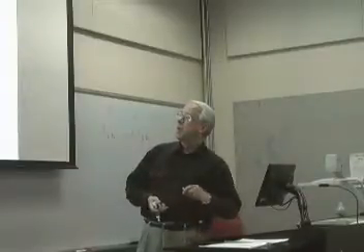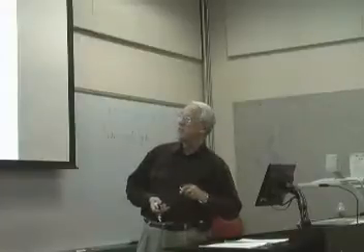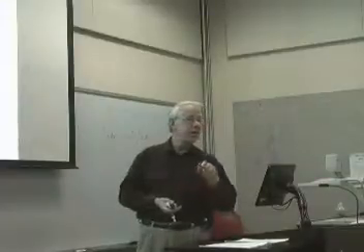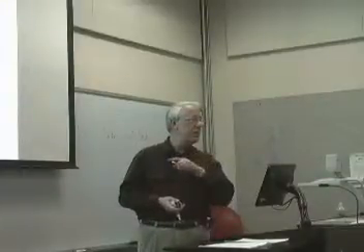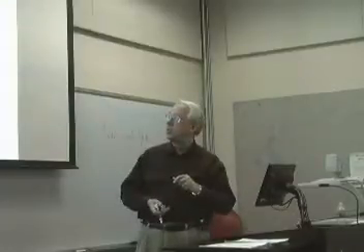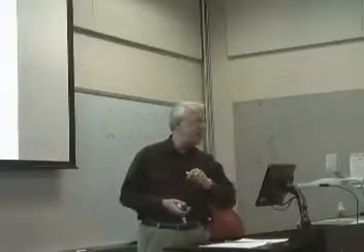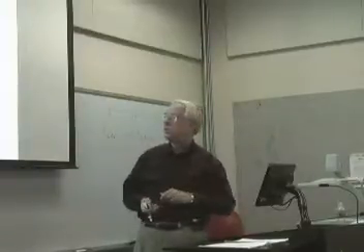This is what happens if you're going to add convection along a boundary. So the flux is just equal to that convection. So wherever you saw that integral term that was added from the integration by parts, you replace that term with this term. That's the nice thing about finite elements. It's easy to embed mixed boundary conditions into it.